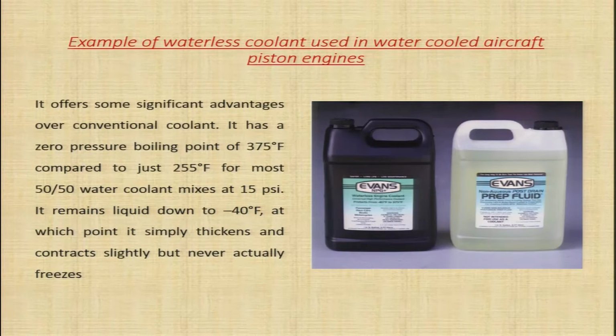Here in the picture you can see some examples of waterless coolant used in water cooled aircraft piston engines. There are coolants in the market where we are not supposed to mix water, they are all waterless coolants, and they offer some significant advantages over conventional coolant. It has a zero pressure boiling point of 375 degrees Fahrenheit compared to just 255 degrees Fahrenheit for most 50-50 water coolant mixes at 15 psi. It remains liquid down to minus 40 degrees Fahrenheit, at which point it simply thickens and contracts slightly but never actually freezes. So, you can see some of the advantages mentioned here.